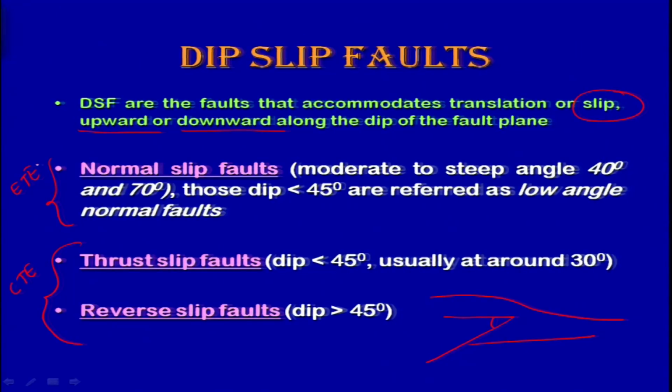Okay, and let me tell you, as I was emphasizing, that you need to be extremely careful while preparing your reports or the interpretation, because you need to know whether it is a normal fault or you are looking at the thrust or the reverse fault, and which block has moved up and which block has moved down. That information will be extremely useful, and you have to do it critically. Okay.